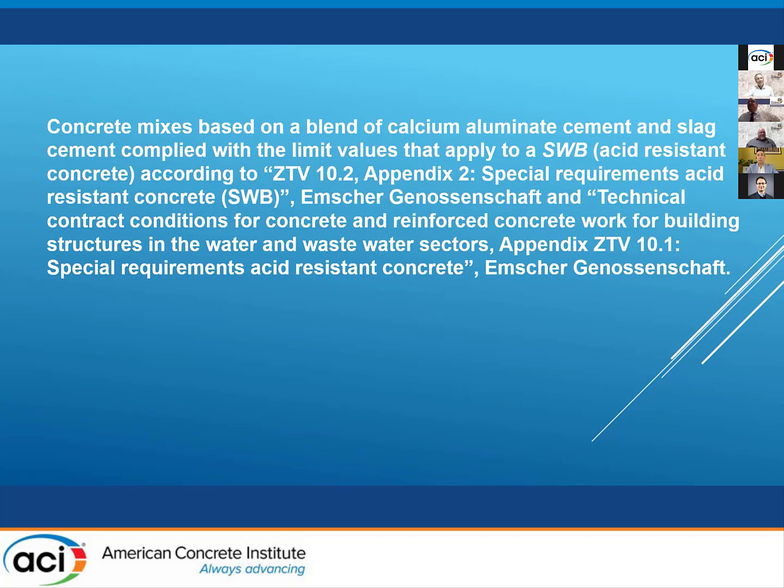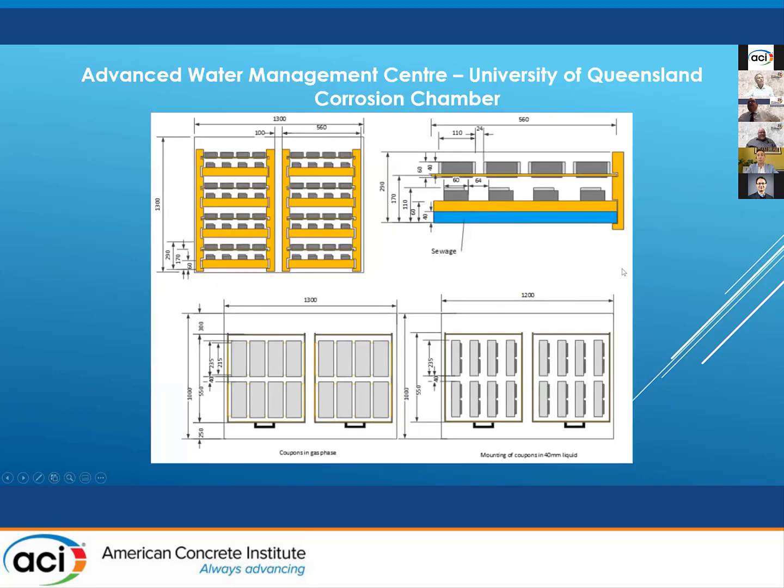basically calcium aluminate cements have been in this area for 70 years or more, but they're expensive and a bit complicated, but diluting them with slag seems to be quite an efficient way of improving a number of properties, including reducing conversion, as well as reducing temperature rise, for example, and cost. So that's something of some interest.